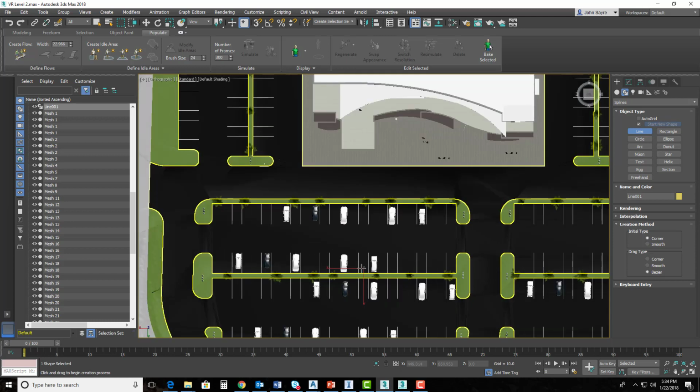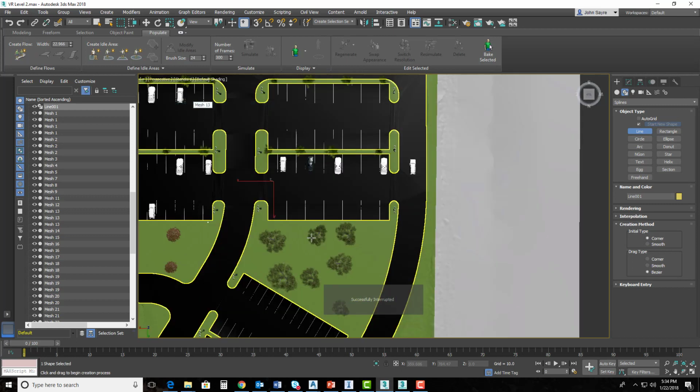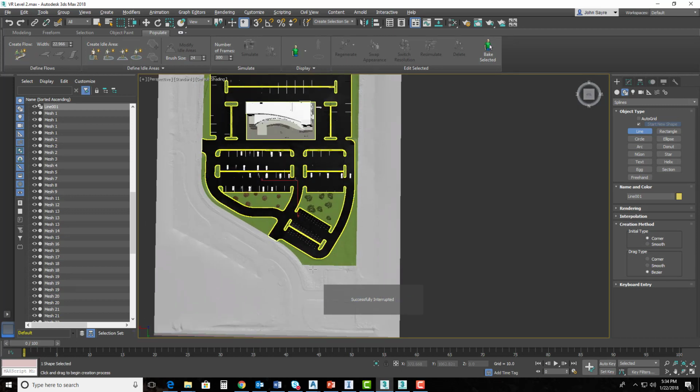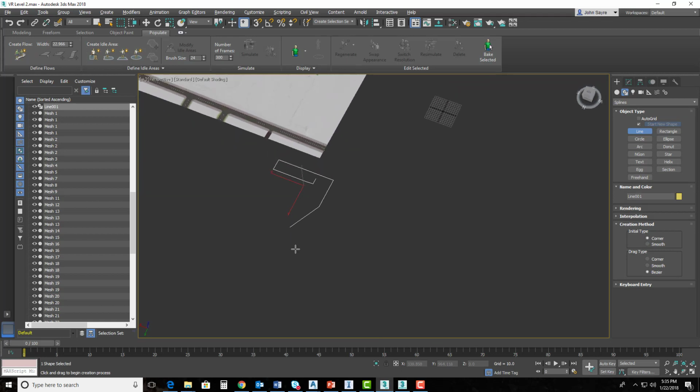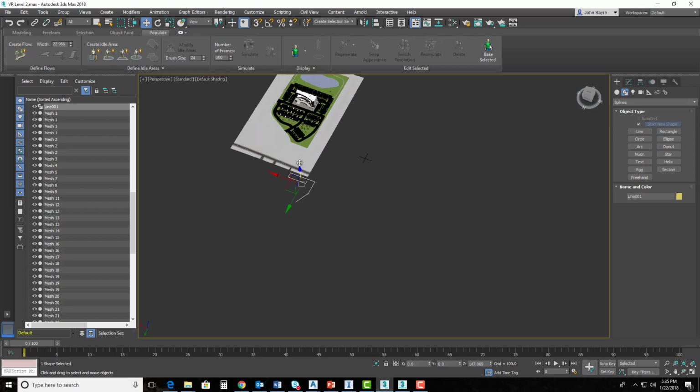If we hit escape, we'll see the X, Y, and Z axis. I'm going to go back to my perspective view, and hold my Alt key down on my wheel again to rotate down. You can see that it's put that line at a different plane, and that's fine. So I can go up and select objects, and make sure that line is picked. Then I can hit the move key, it's up here in the toolbar. I can grab that and move it up, and it will be in the right location.